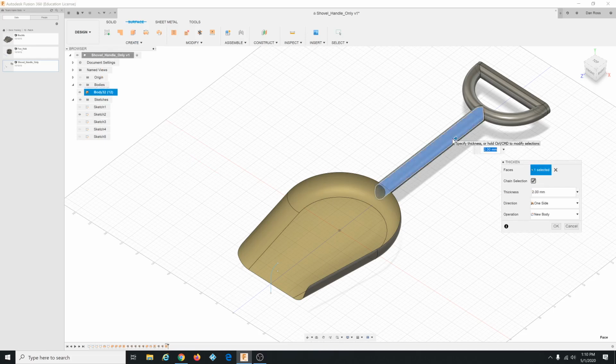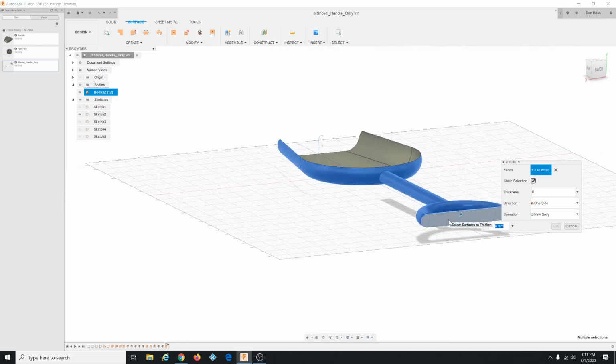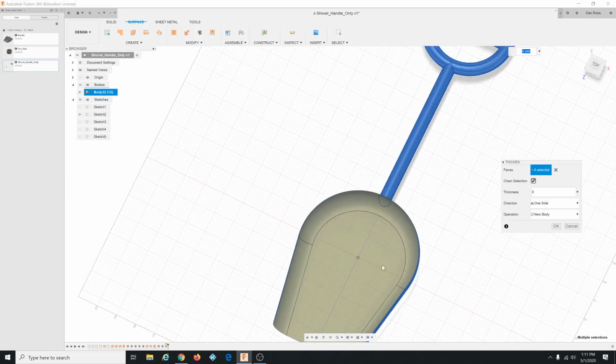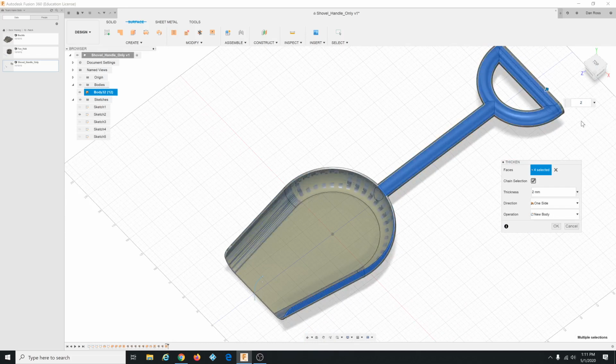click this thing. Now, I started getting errors unless I change thickness to 0 first. Okay, then hold down Shift and click the rest. You also have to orbit around to get this backside, and then hold down Shift and click it. Okay, so I've got 4 objects selected at 0 thickness, and now I can add the thickness. You can type in a 2 in this dialog. Okay, so you got to be careful with the order. Just play around with entering the data in here until it's working right, and then click OK.